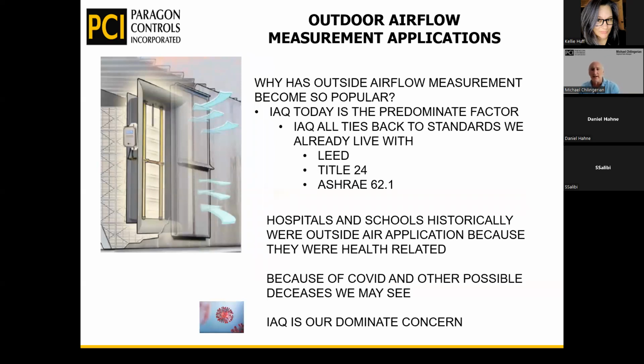Let's take a look at outside air. There's a lot of different concerns about outside air, especially when we're talking about rooftops. And there's so many different types of rooftops out there. In a lot of cases, it could be with a hood. And if it's a hood, is there a single hood or are there multiple hoods? In a lot of cases, there could be a louver. Is there a vertical louver or a horizontal louver? So how we're going to do airflow measurement is affected by the physical properties of the device that we're actually working with.